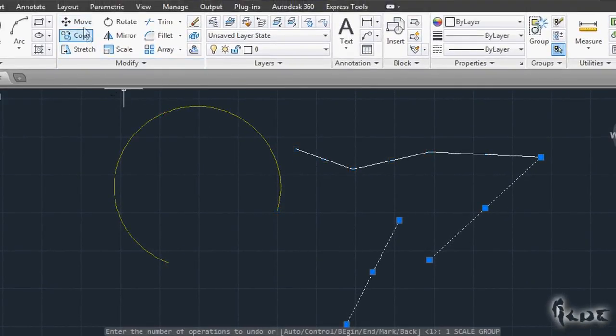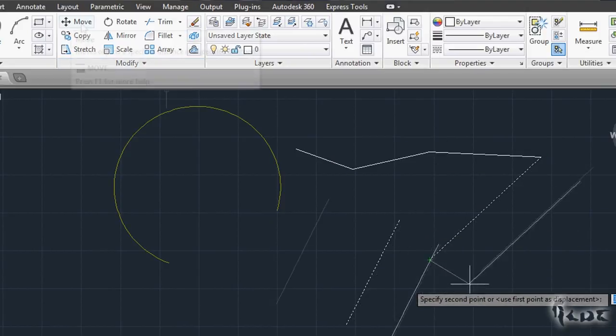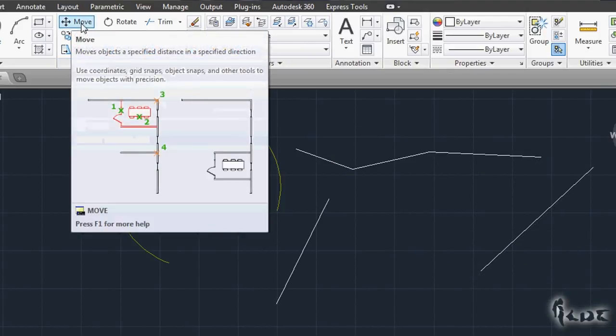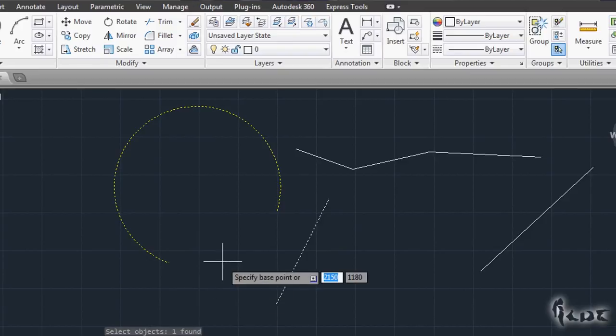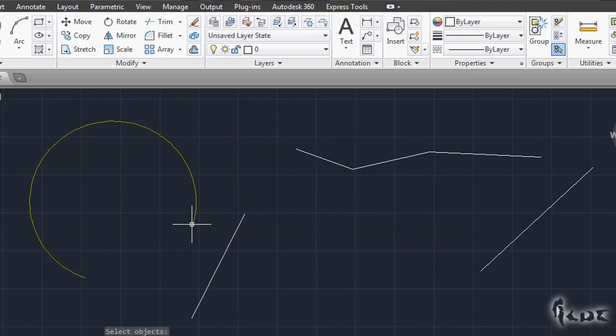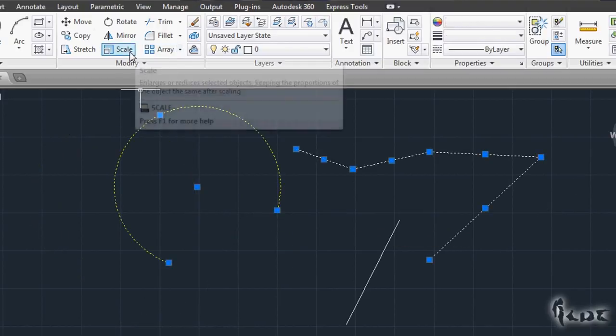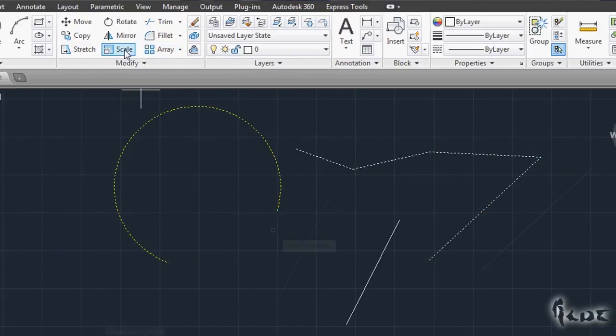If you have already selected the objects, you can go on with your transformation. Otherwise, the software will ask you to select the objects first, and the pointer will turn into a small white square. After you made this first step, press Enter from your keyboard to go on with the editing. For example, if you choose Move, click on a random point and then move the mouse until you are satisfied. You can stretch or scale objects using the other buttons in this way.